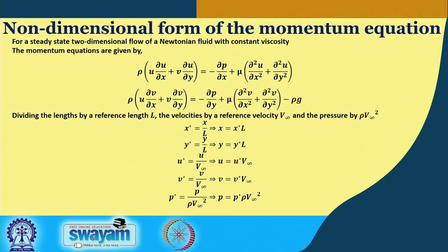For pressure, generally we do not have any explicit equation when we talk of the Navier-Stokes equation. Generally, pressure is taken indirectly through the continuity equation, about which I shall not be talking here. In other courses, like CFD, it is taught how we can take the pressure variation into account. Now, with these assumptions, let us look at this particular situation. This is the x direction momentum equation, and this is the y direction momentum equation.